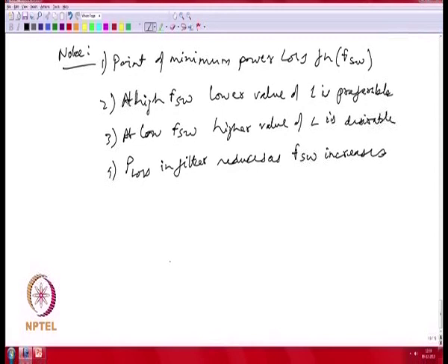So, your overall switching frequency in your design can be justified, because in many designs you often ask what is your switching frequency, and you might say 10 kilohertz or 20 kilohertz or some number. So, later on you can actually justify why you selected a particular switching frequency through such a loss calculation, which leads to the best switching frequency at which the power converter can operate.